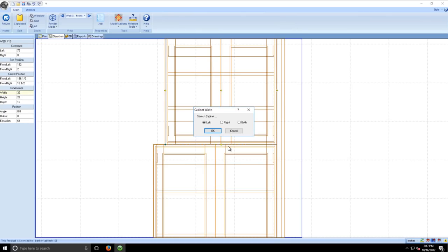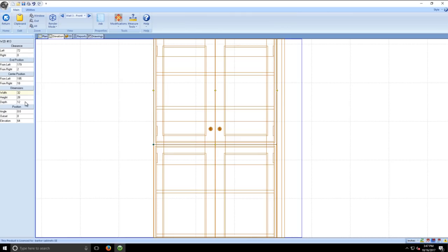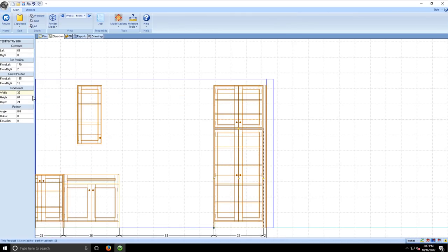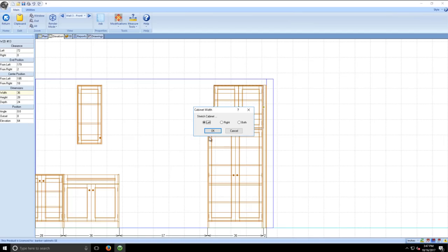Now, the width you can do on these tall cabinets, you can do whatever you want. It doesn't really matter. Typically, I'd keep them between about 28 and 36 is a pretty good goal. Let's go 36 because it's going to look better. And depths of your tall cabinets can be 24 inches, which is what I see a lot of people ordering them at. But I like to recommend that you order your tall cabinets at 26 inches deep. And I'll tell you why here in a minute. So the wall cabinet's 26. And the lower portion is 26.